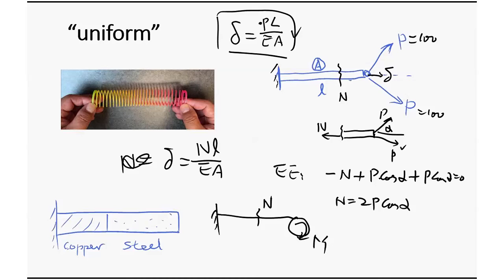Then maybe you end up with the cable feeling nothing. So these two persons fight each other there, and the cable may feel nothing. Then the N will be 0, right? So you have to find the internal force in the cable to be able to calculate the elongation of the cable. How would you solve for that? You just have a moment. Oh, that's something we can solve later on as an example, right? You use the equation of equilibrium, solve, find out the N. Right.